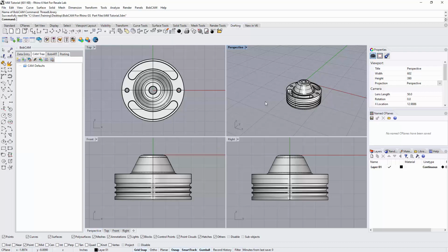The thing with lathe is you don't really vary how you set your parts up. Your part's always going to be set up with the front face of your turning part kind of right here at the XY location, or really it's XZ when we get into turning, but we can adjust that. And we'll look at an example of a turning tutorial later on.